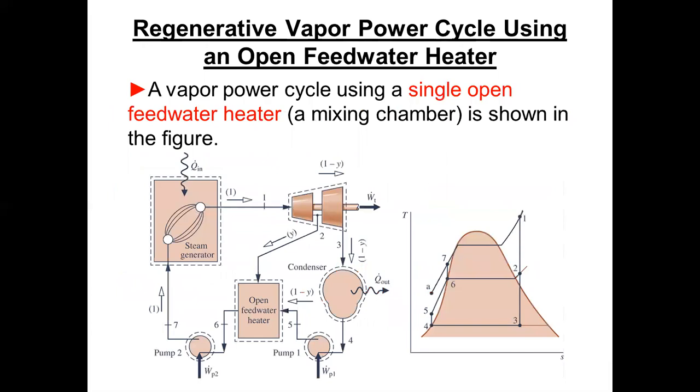Okay, so this is what we get into on the regenerative cycle. Notice that we have these little numbers in parentheses. Where we come out of the boiler, we have an arrow pointing toward the high pressure turbine, the first section of the turbine, and we have a 1 in parentheses. That 1 means that we have the entire mass flow. I call it main steam flow, usually out of the boiler. So that's the maximum steam flow in the cycle.